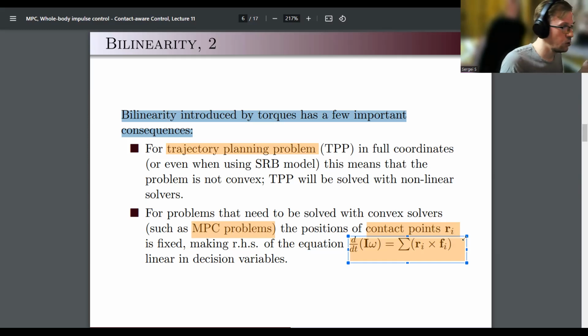Is it going to be a good law? Maybe not. But you remember last lecture we studied how to compute step length using desired velocity. The Raibert controller is what we called it. That is a powerful way to decide step length. And if you can decide step length, you know the position of the next step.